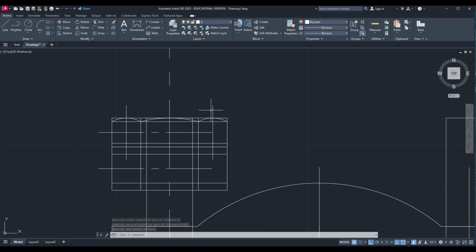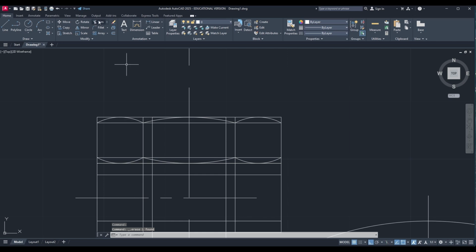Now I don't need these two center lines, so I am deleting them. Now I will mirror these curves which we have drawn to the down by using the horizontal center line which we have drawn. Two endpoints of that horizontal center line, erase source of this now. Now I don't need the center line, so I am deleting it. I will trim off these extra parts which are there. Now showing it in detail. First one I will show, then I will skip the other things.